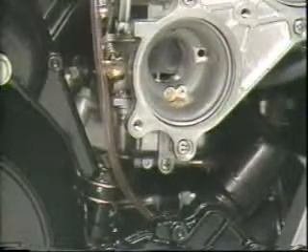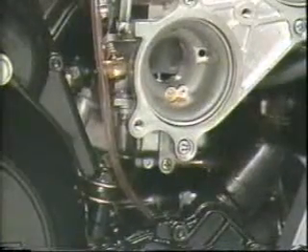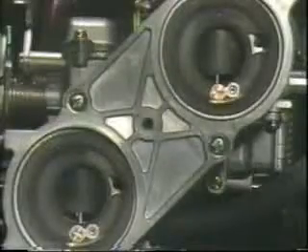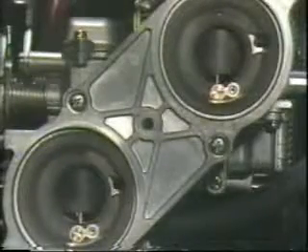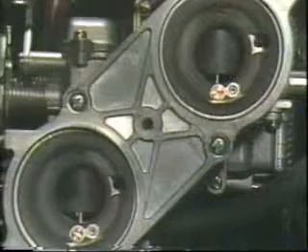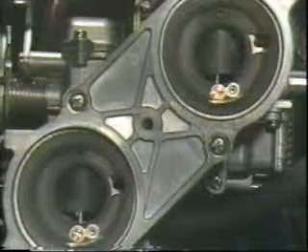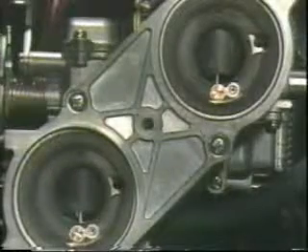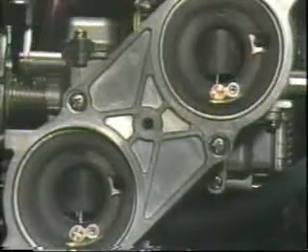First, check each of the 4 carburetors and see if there is fuel there. Also check the fuel level in each carburetor. Then, check if the free play of the throttle cable is appropriate. The next item in troubleshooting is to check if the carburetors have been synchronized properly. This can be done by comparing the heights of the throttle valves. The heights must be the same for all 4 carburetors.